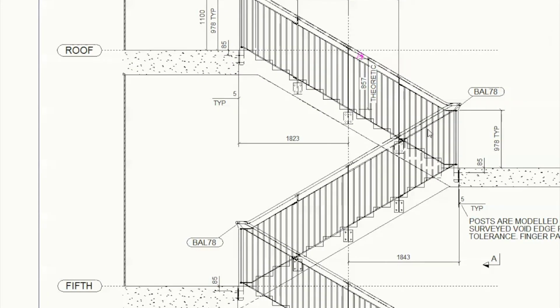And then they're going to mount the central void posts, which are loose. They're going to bolt the three panels together, and then literally just suspend them in between, and then pull up on the middle. It's going to sag when you do that, and they're just going to pull that up till it's at the theoretical level or till it looks okay, and then put a single fixing in there, and then just follow up with the rest of the fixings, and they're going to continue with that.